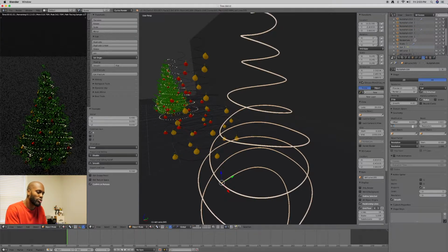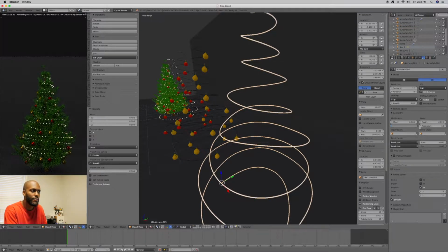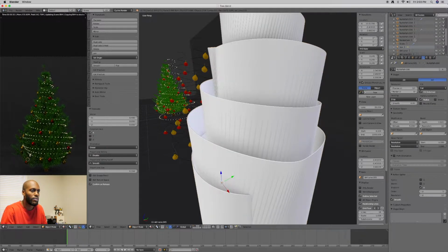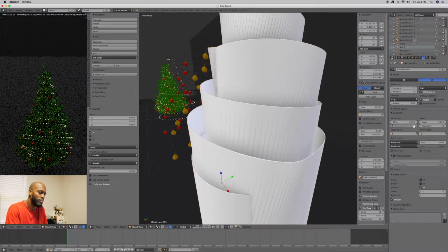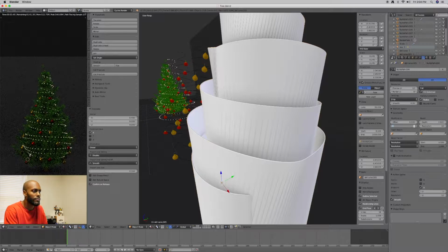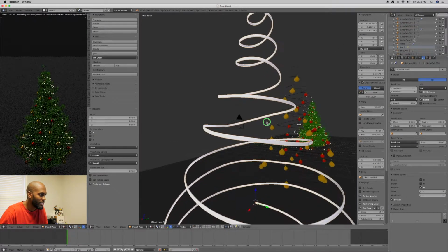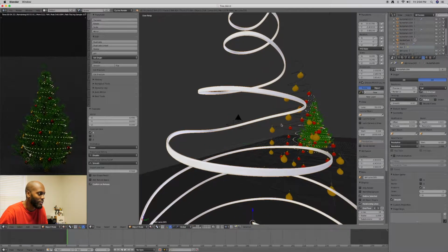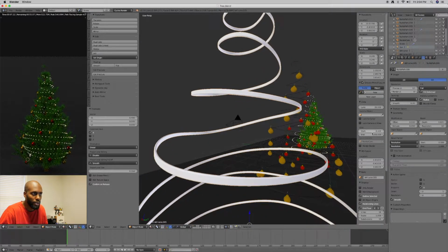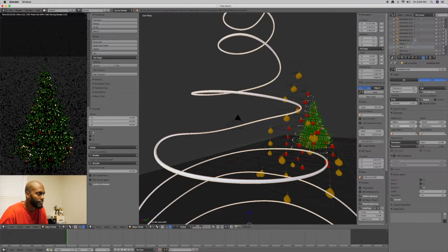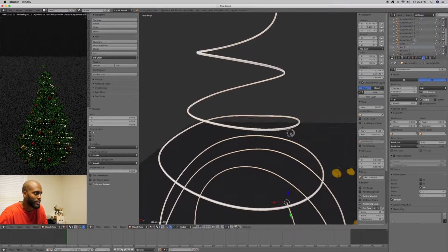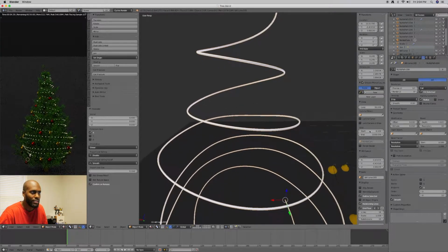We're going to do some extrude on this one, so let's do 5. Oh, not that bad. We want 0.05. We don't even want that. But you can see it's creating a shoestring effect, which is kind of cool. But we don't want that. So 0.01. I can live with this. Actually, let's just leave it at 0. Let's just keep it circular.